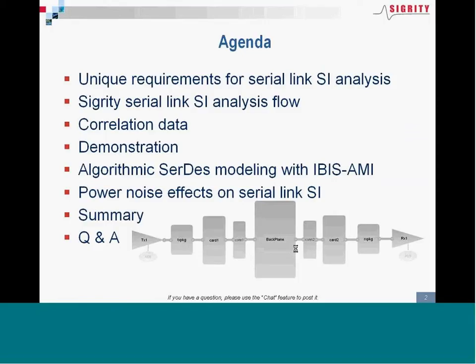We'll see a little bit of correlation data. In the middle, we're going to take a break to do a brief demonstration and run the tool through its paces and show some of the capabilities there and some of the different trade-offs that you might make as an SI engineer working on these types of designs. We're going to talk about algorithmic SerDes modeling with IBIS-AMI. We've had lots of questions on that. Power noise effects on serial link signal integrity, and then we'll go to questions.